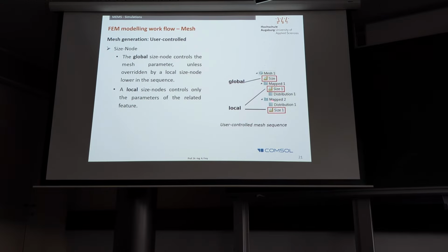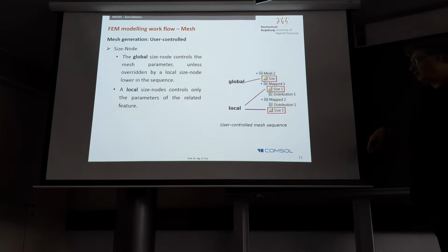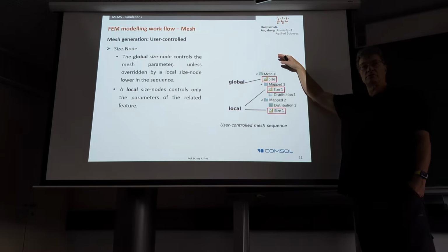So if nothing is specified, always the global mesh size determines what is going on, but you can override by these local size nodes.